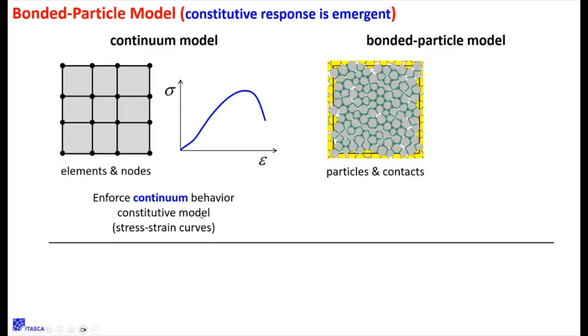We call these things constitutive models. FLAC3D has maybe one of the most comprehensive sets of constitutive models for rock failure. I don't know, there are probably at least 12, maybe 15 different ones. Sandstones have a certain type of constitutive model that reproduces sandstone behavior, because remember, sandstone has pore collapse, so there's stuff that starts to happen. It's much more complicated than just granite. Other types of rock have different constitutive models, so you choose the constitutive model based on the kind of rock you're trying to model.